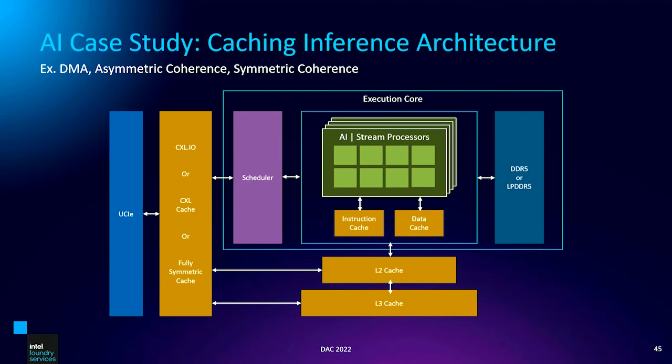So what I see happening in the world is two things. Number one is, in the case of modular AI or stream processors, a lot of people use RISC-V or ARM cores as a babysitter. And the other thing people are doing is taking RISC-V, and because it's an extensible instruction set, they're either using the vector definition from RISC-V or doing their own to create their own graph or stream processors. That's one of the things you can do with RISC-V that's very difficult to do with x86 or ARM, because you can't change the ISA, right? So anyway, I see that as a very clever thing that's going on with RISC-V these days.